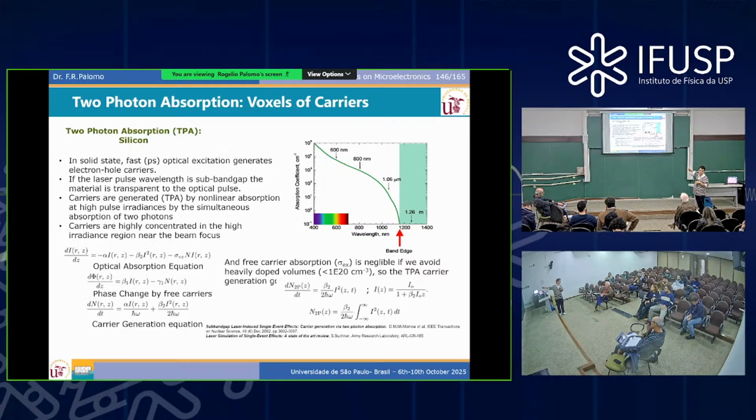Beyond that, the silicon is transparent, with the exception of the focal point, where the intensity is so high that this term is dominant. If alpha is in that regime, alpha is basically 0, so you only have that term to explain the carrier generation equation, the absorption. You have to do a lot of quantum electrodynamics in itself. Okay, you do it, and that's the result.